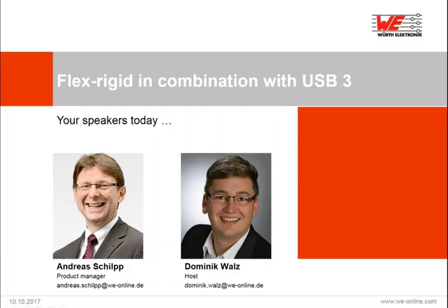And so, of course, due to the different specification, you need additional lines for LVDS, and this needs 100 ohms differential pair constructions. So that's not the same. It's used for different protocols and different applications, but it's possible to combine this in one design.